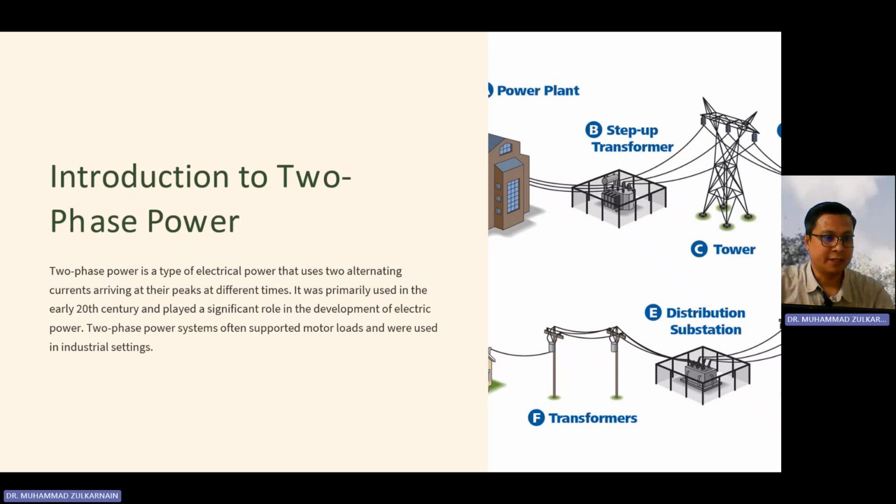Last time in week 4, I already explained, we have two poles with two windings, and this is similar in characteristic to the sinusoidal system principle, where at the angle of zero the induction will become zero, and then we come to the pole at 90 degrees, and then we come to positive induction. And if we complete one cycle, it means we complete a half circle on the top and a half circle on the bottom.